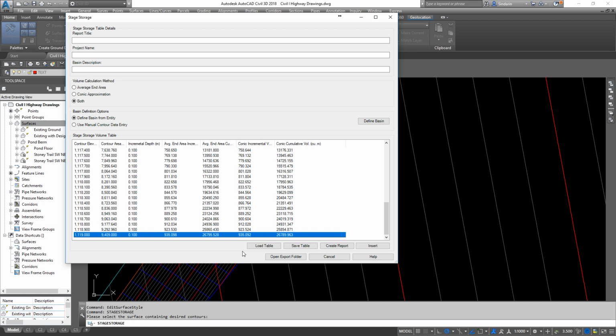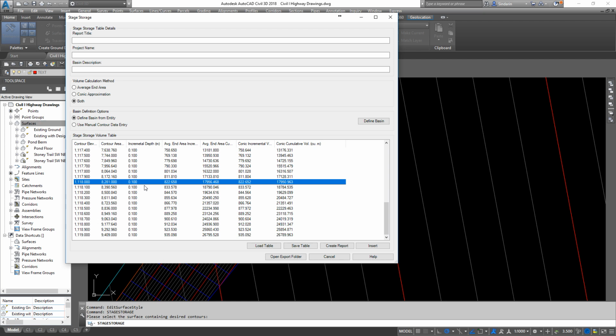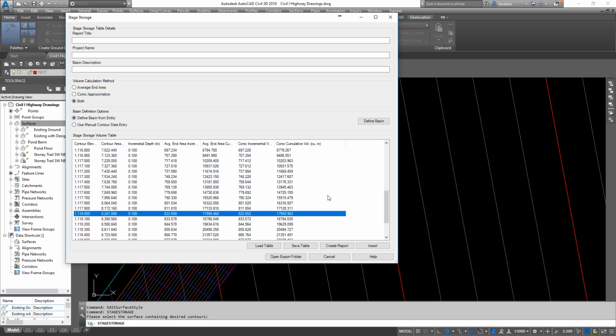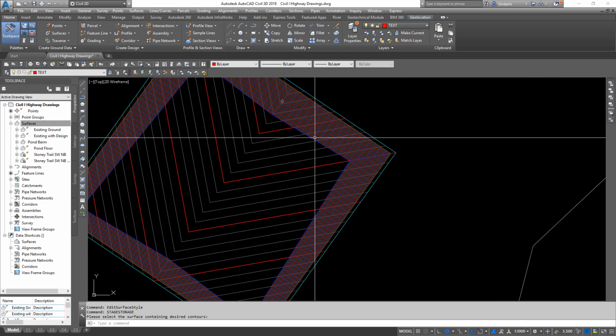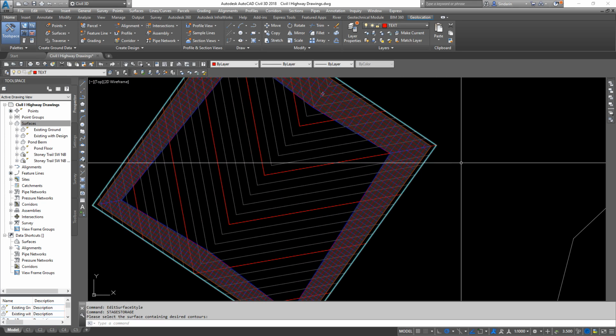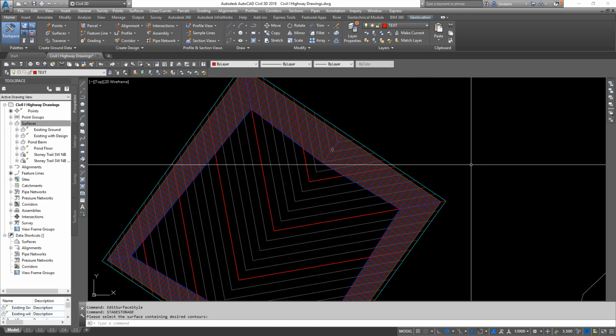But the top, give or take half a meter to a meter of a pond, we can't really hold any water. That's for freeboard, that's for additional storage, just in case. So if I say select 1118, we're down to 17,950. Now this is a little bit higher than we wanted, so we can go ahead and modify. So I'm going to cancel this. And I'm going to, let's get the outside berm built first, and then we'll decide what we want to do for raising or lowering.